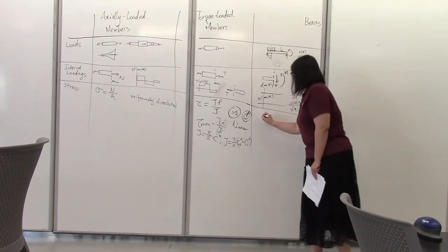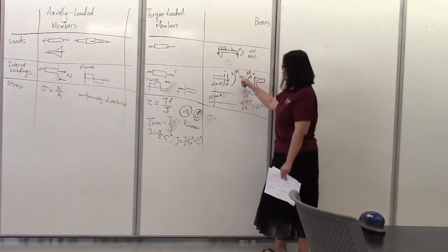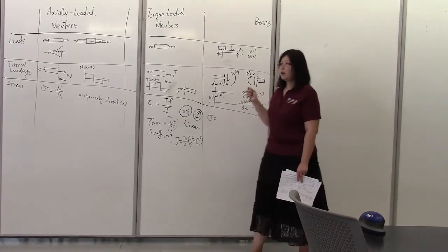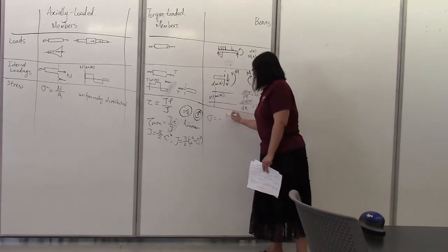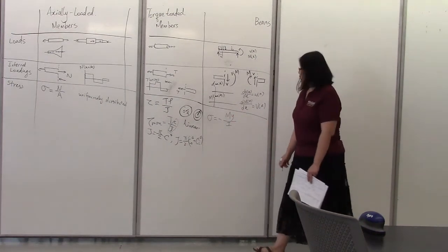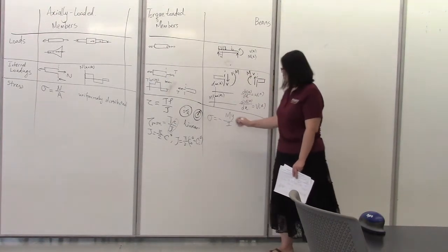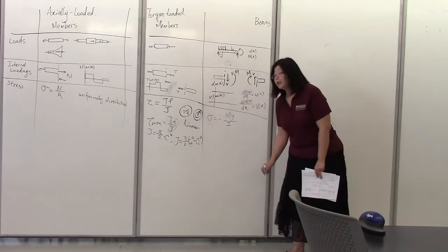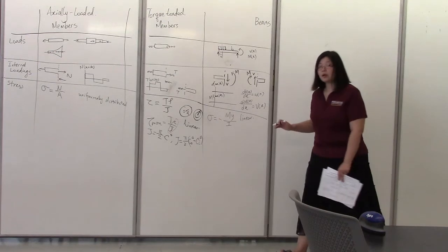Now for beams, we have what we call the flexure formula. For this course, we only consider the stress due to the internal bending moment M. The internal shear force would cause what we call the transverse shear stress, but that is not discussed in this course. So the stress created by this internal bending moment M is a normal stress, which is normal to any beam cross-section. And it is calculated using negative My over I. This distribution is also linear with respect to not the center anymore, but an axis, which is called the neutral axis.